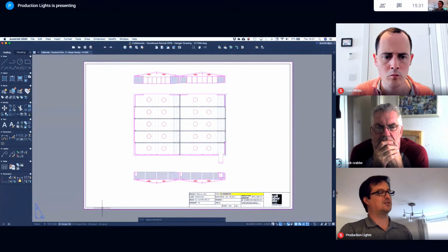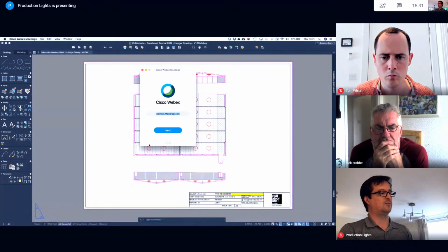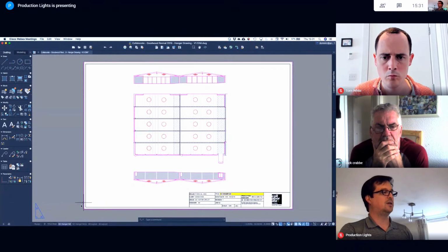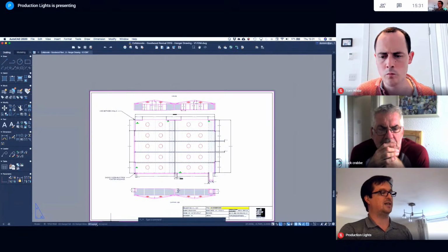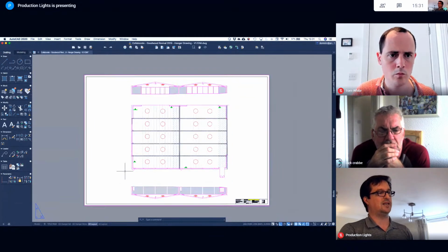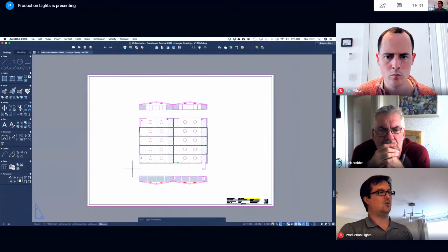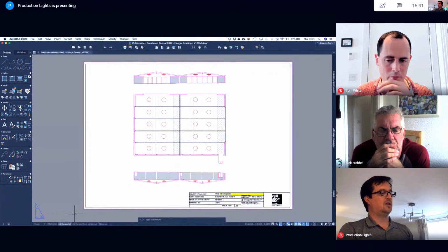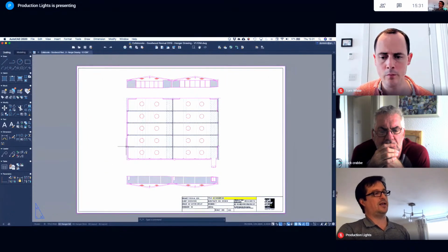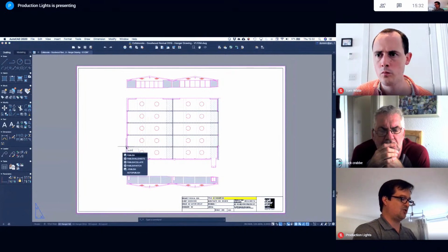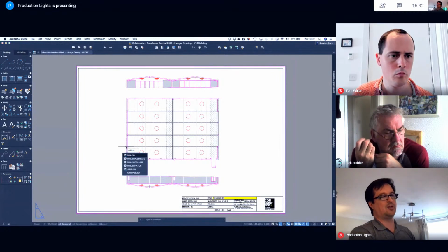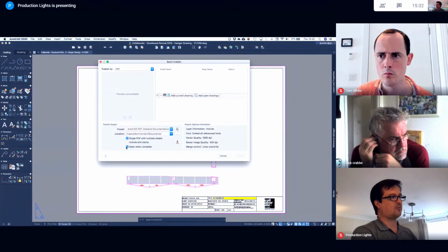And then we've got some layouts. And actually the layouts in here are all the same. Click away, Dom. Come on. So we've got an A3, some A3 detail. I've got an A0 waiting there for them to plot, and an A1. So going back here, we can come in here and go, here's a drawing. We want to send it out to the client, and we want to publish a few sheets together. So it's exactly that. Command line, publish.